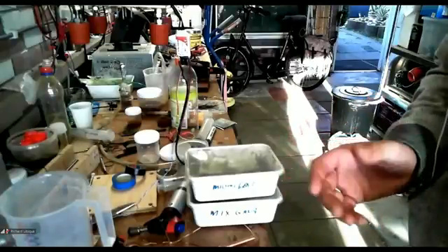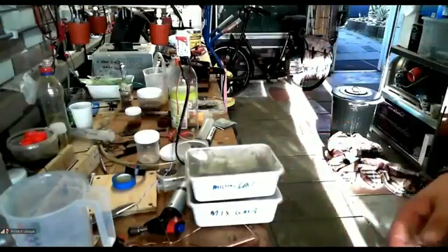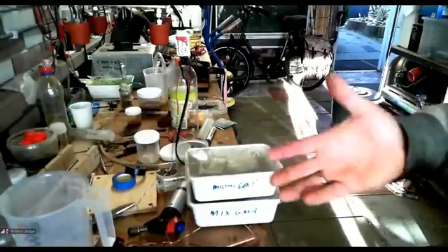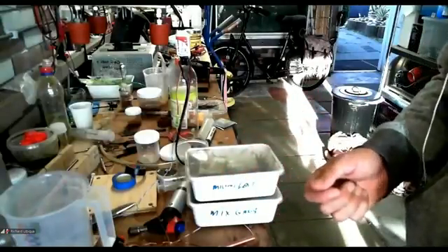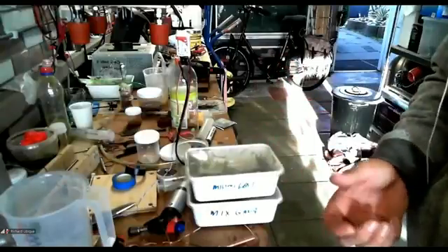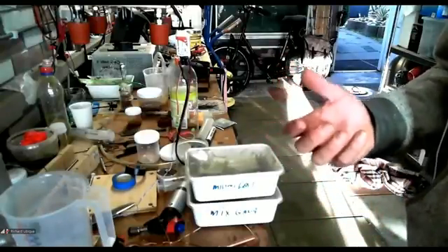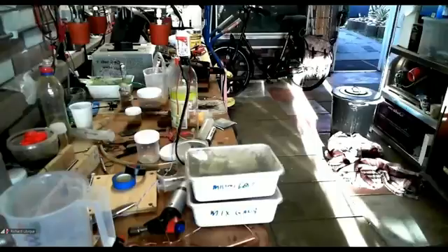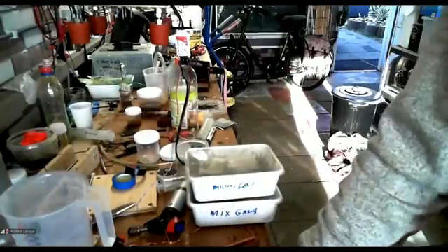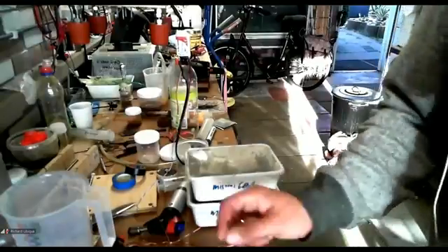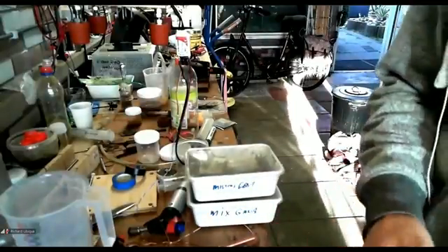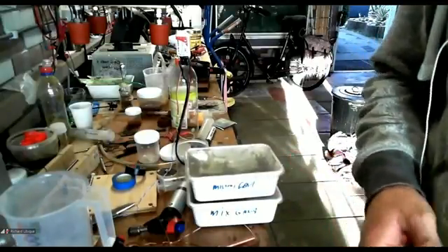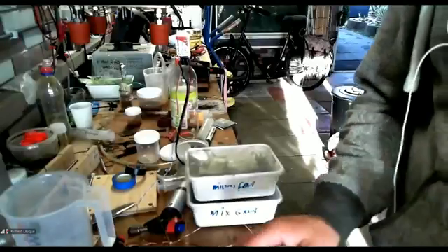So you adapt a bit, and then you do it again, correct your mistake, or correct what has been happening there, and then you go into the hanging procedure, where you just keep the caustic there to vaporize and to keep it hot and to maintain an environment where this caustic can actually have a reaction with your coils or your products that you want to nanocoat. And you keep monitoring. It doesn't say you have to do this 5 times or 3 times. It can be done in 1 time if you're doing a hot caustic procedure. Did that help?